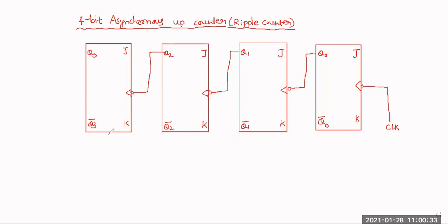Yes sir. For all the flip flops, I want to make the initial values zero. So to make them zero, which input will I apply? Clear. Okay, so I will apply this clear. This is your clear input, that is your CLR prime.